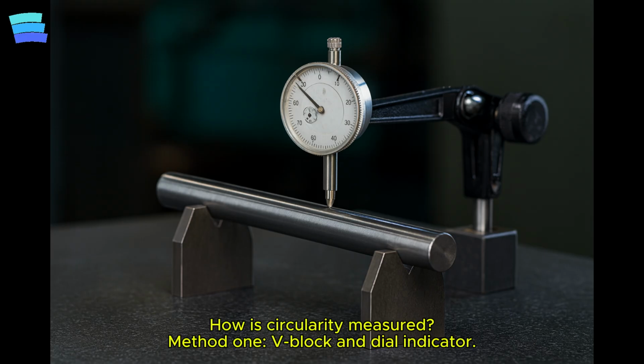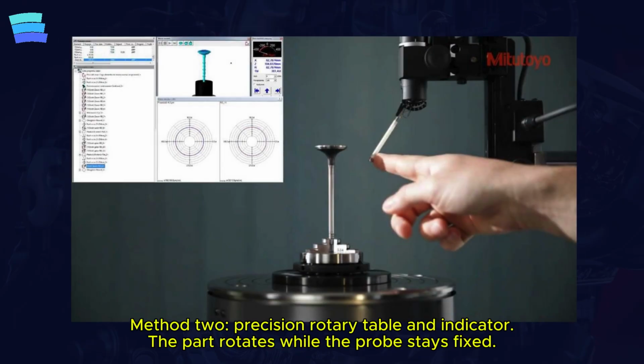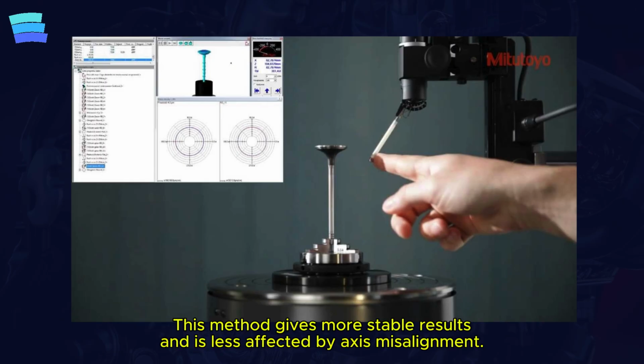How is circularity measured? 1. V-block plus dial indicator. The shaft is placed on a V-block, rotated by hand, and the probe scans the surface. The difference between the maximum and minimum readings on the indicator is the circularity value. 2. Precision rotary table and indicator. The part rotates on a precision rotary table, the probe remains fixed. This provides a more stable result and is less affected by axis misalignment.